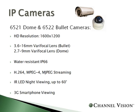Both of these cameras are going to boast a high HD quality resolution of 1600 by 1200. That's 2 megapixel quality. Both of them are going to offer a varifocal lens, which implies that it's a manually adjustable lens, so you can set it to the specific application you need and then walk away from it. Water-resistant outdoor rating for IP66, as well as multiple compression methods, similar to the 3 we talked about earlier, H.264, MPEG-4, as well as Motion JPEG.